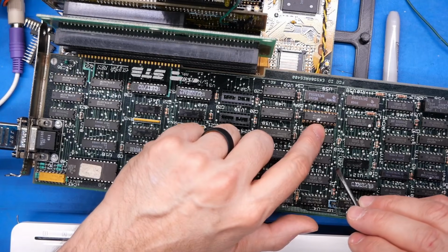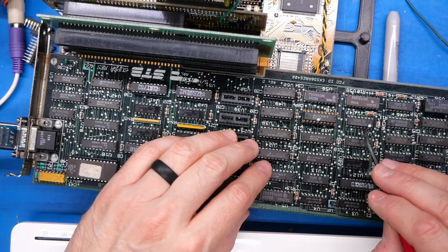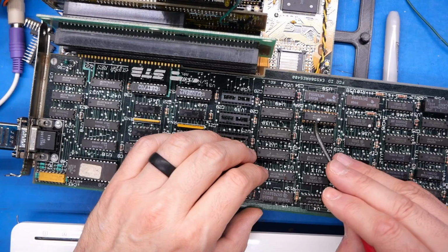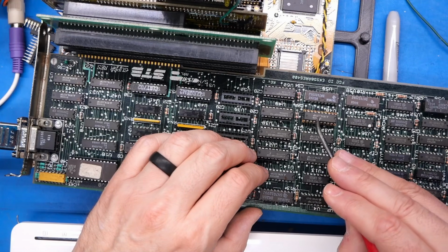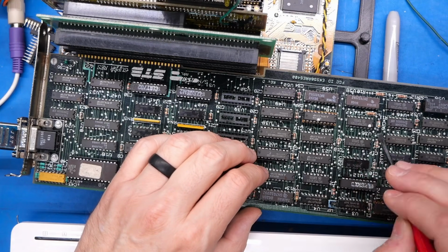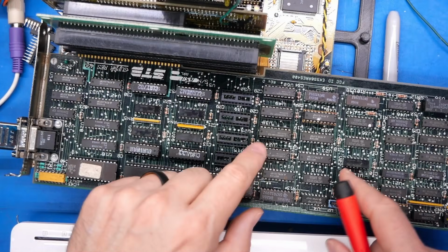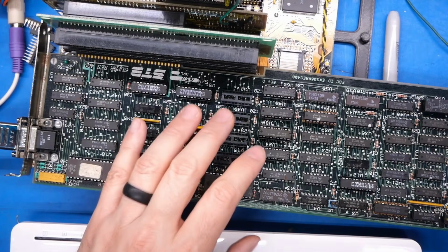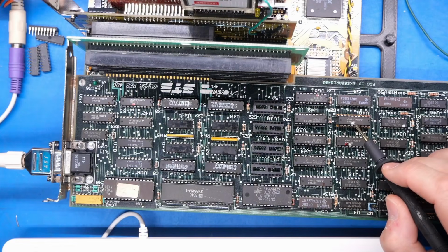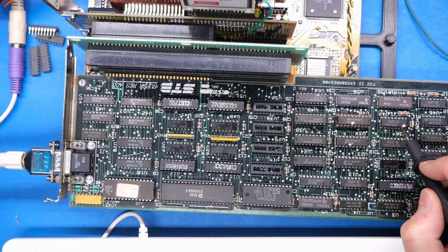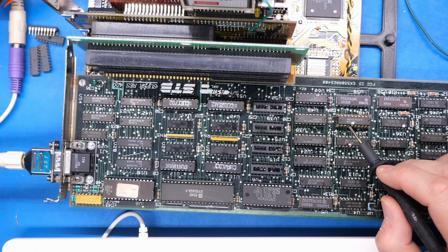So we know that this is the output pin for the bit that's having an issue, and it goes into there. So we need to find where this pin, which is the input for this unit, is going, so that we can figure out which chip that goes to and then try to make heads or tails of what we're seeing there. Okay, so we know that's the output. That was the one that goes over here. That was having an issue. This is the input pin.